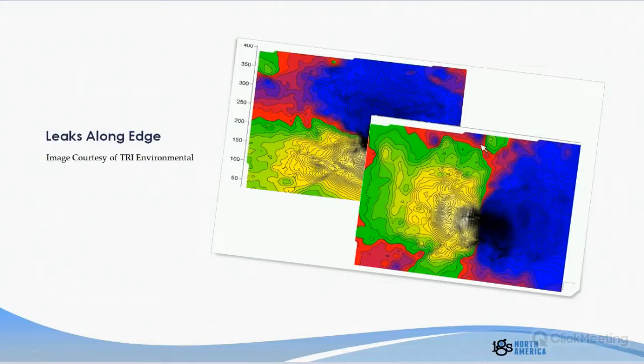And so this is our current injector. We got positive on the left, negative on the right. So what we're looking for is negative on the left, positive on the right. And then we see it again here. But then we see this hole right here that barely shows up on this map. You can actually see it. There's a little negative peak right here, which is easy to miss because it's a negative peak in a negative area. But once we plot the perpendicular file, we can easily see that leak pop up because it's essentially like taking a dipole and walking along the edge here.